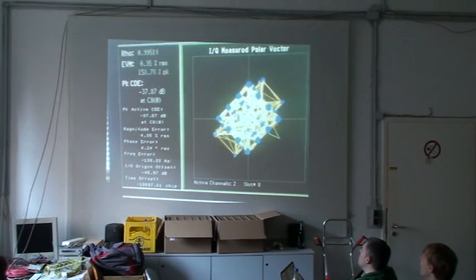This is a constellation plot of a UMTS beacon, and it is the sum of many QPSK signals. As you sum together lots and lots of QPSK signals, they form larger and larger grids in the I and Q space. Which is an example of a real-world case of QPSK gone mad.